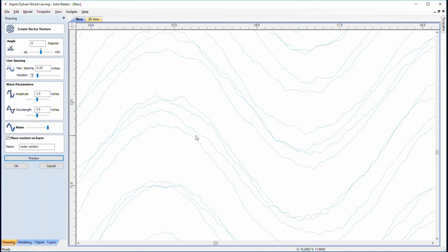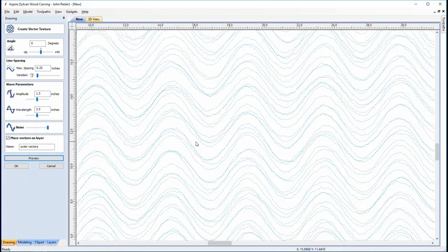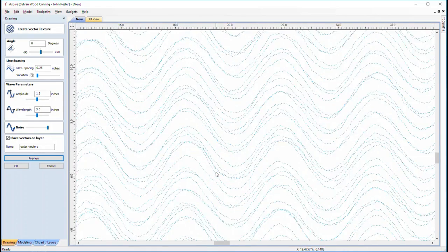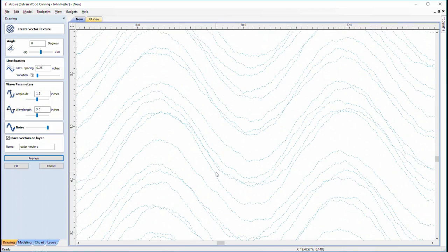And then if you look down in here, you're seeing a lot of erratic behavior moving back and forth between the lines. Now I bring that erratic behavior up because if you decide that you want to do something like this, you need to remember that just because you're running lines across the length of the material, the erratic behavior is going to cause a lot of back and forth movement in the CNC. So what that's going to wind up doing is turning the duration of the cut up considerably. Okay? So that's pretty much how you do that.